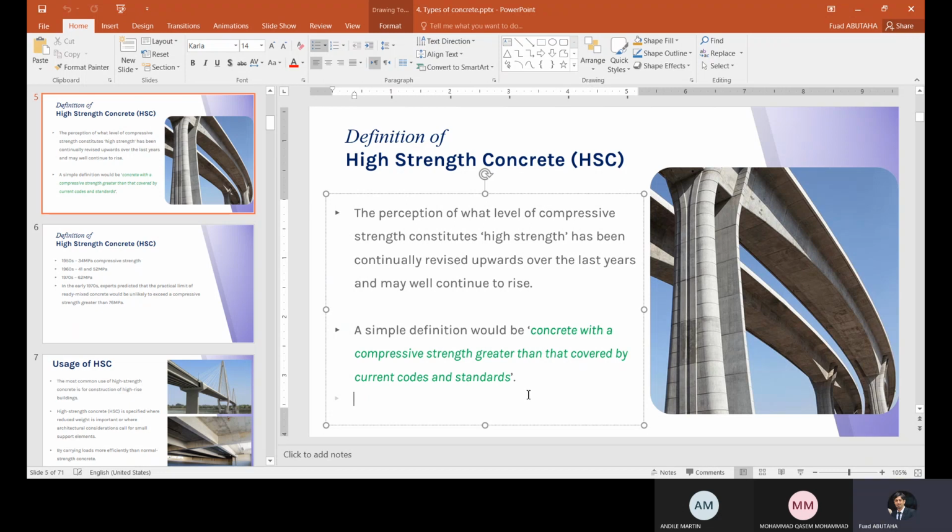They can also provide information that helps in the selection of the aggregates in the concrete, and it is well known that using a low maximum aggregate size can also increase the compressive strength of concrete. The higher the maximum size of aggregate, the lower the strength of concrete.